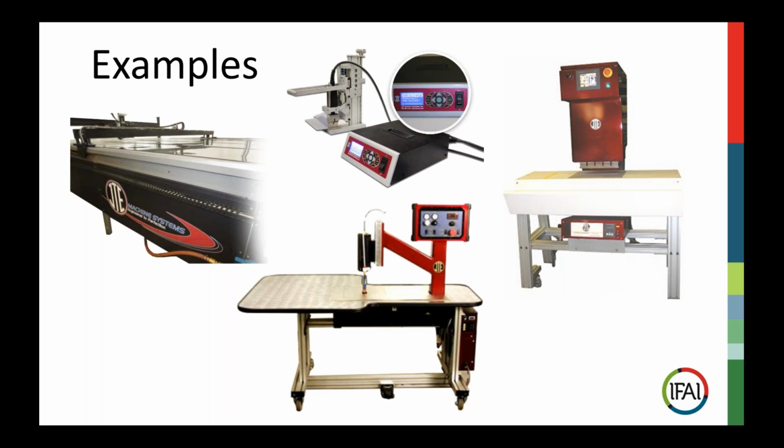On the middle top, you see our handheld, and that is, again, very handy in tacking, small format welding, and everything in between. On the right is the sonic bar welder, which is, again, fairly unique, but here you can weld about 11 inches, and that's about the max of a reasonably priced generator that you can weld, 11 by ½ inch. And then on the bottom, that is the example of the machine welding the bulletproof vest. It's actually welding and cutting at the same time, much like a sewing machine, but with very little skill needed and, of course, no thread.